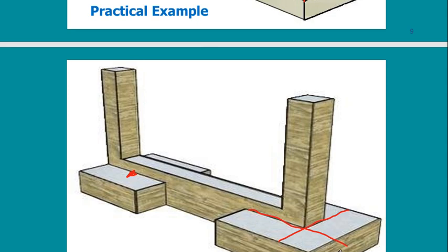This is another line I can check. Of course, according to my dimensions, I will know which is more critical. Usually this is the critical distance, so I calculate the shear at this line. Here I don't have shear in this direction, but I may have shear in this direction. So I will check which is the critical and check the shear.